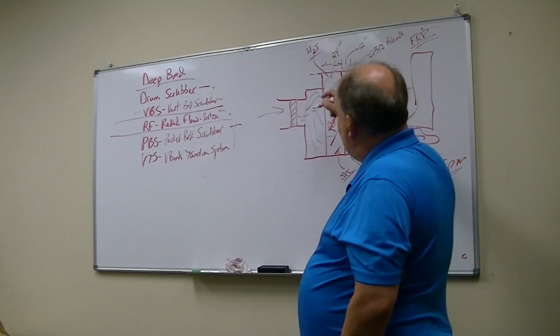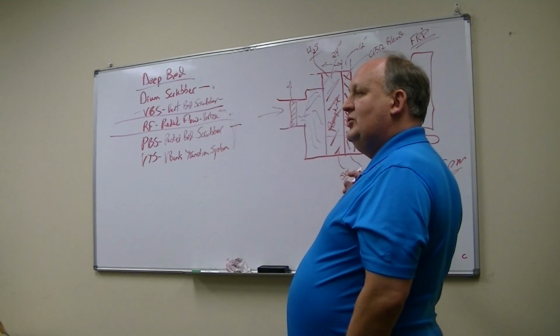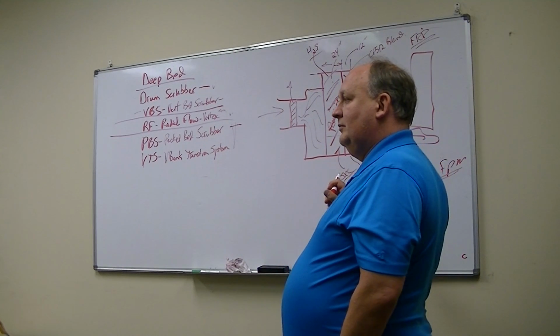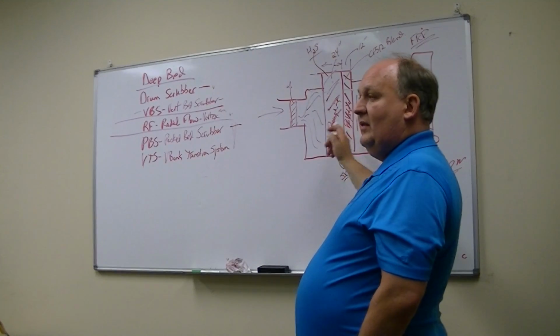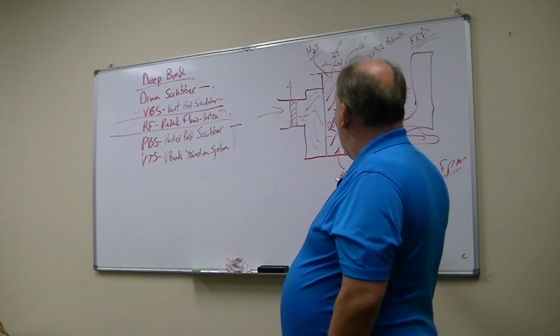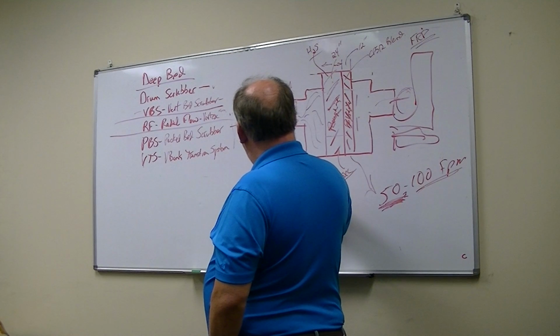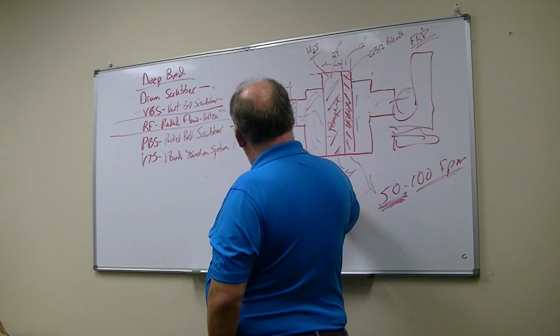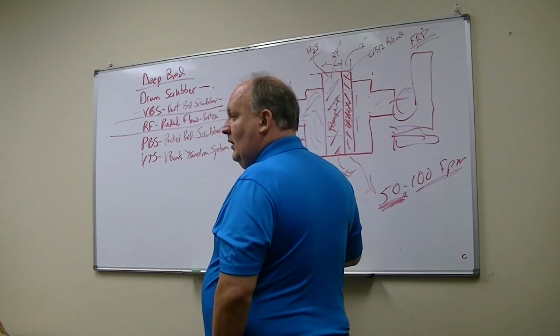So the key is this mist and grease filter operates at a much different airflow rate, okay? Then we send the air through the media. So the airflow rate for this mist and grease filter typically needs to be basically 300 to 350 feet per minute, okay?